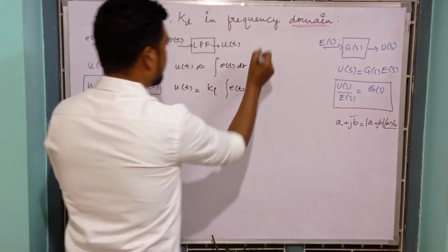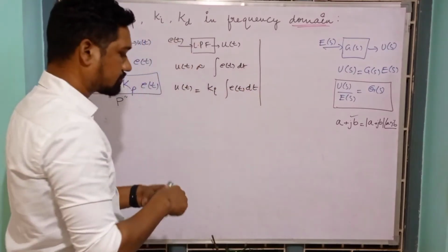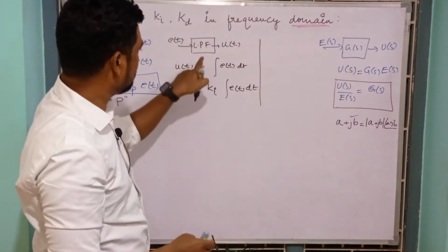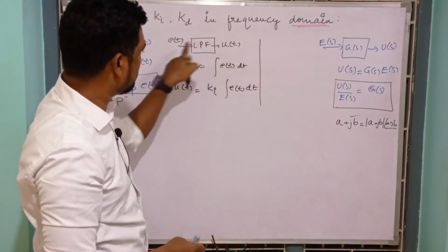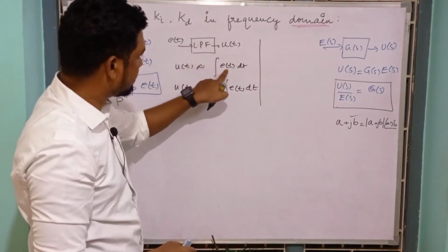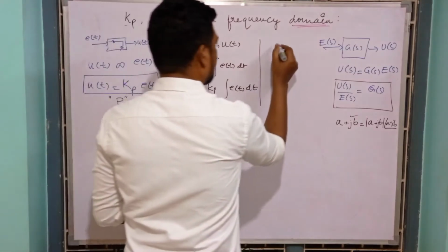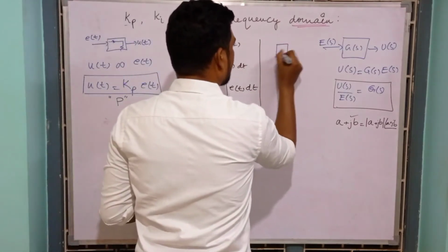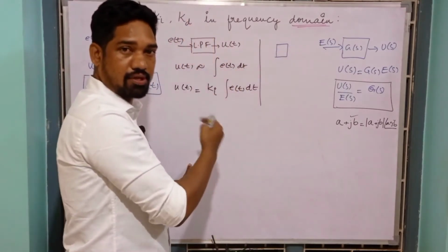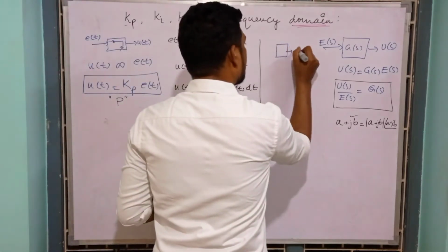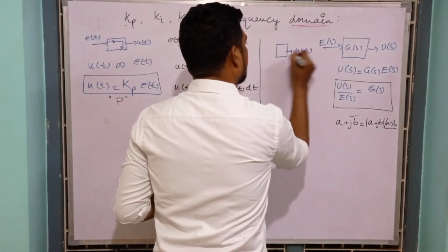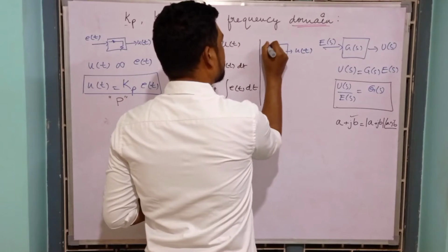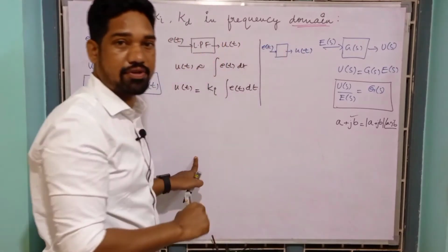And on the other hand, guys, considering low pass, the output is directly proportional to the first integral of the input. So high pass, another circuit, another network, another system whose output u of t is directly proportional to the first derivative of the input.